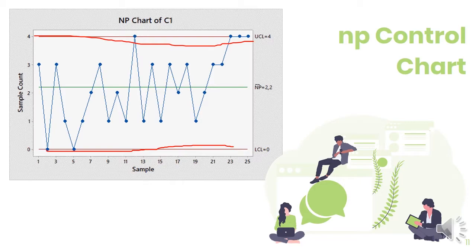But there are several data plots that fall exactly at the upper control limit. There could be insignificant assignable causes that need to be examined along the process, because those data are at the farthest bound and could almost make the whole process considered to be out of control.